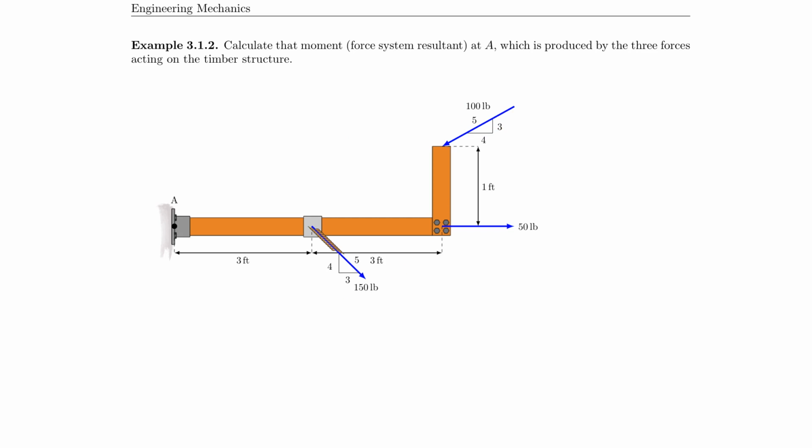So let's go ahead and do that, and let's memorize again that our moment is really equal to the sum of the forces times their perpendicular distances, right? So I now have to look at these forces and really break them down into their perpendicular components. That I believe is easier in this case. So I, of course, could take this force and extend its line of action. Let me show that to you graphically.